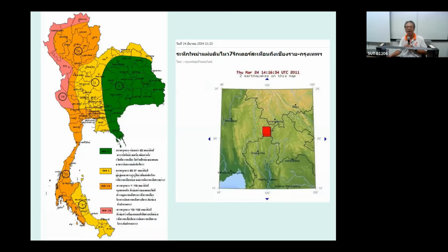The easiest way to say that your column will be very strong is if your column is big. Okay, and there are portions of Thailand that you've got to consider, in Kanchanaburi, in Tak, in Mae Hong Son, in Chiang Rai. Okay, this pink color, you've got to design the structure because this is going to be an earthquake-prone area. Usually you've got to put about 20% more reinforcement into your beam and column to make your beam and column stiffer than normal design.